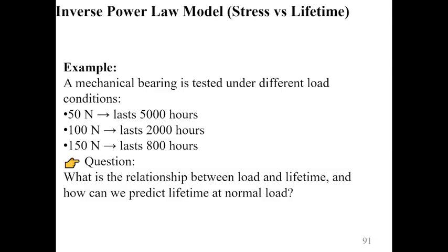This is an example related to the inverse power law model, stress versus lifetime. A mechanical bearing is tested under different load conditions. 50 N lasts 5,000 hours, 100 N lasts 2,000 hours, 150 N lasts 800 hours. The question is what is the relationship between load and lifetime, and how can we predict lifetime at a normal load?